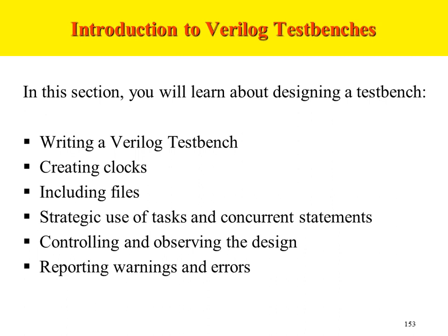We have seen for a while now how to write Verilog designs, or how to describe various circuits using the Verilog language. Once you describe a circuit using Verilog, you would like to test it to see whether the digital circuit works correctly as per the expectations or not. So how do you do that? You write a test bench, that too in Verilog language, and using the test bench, you test the functional aspect of your design.